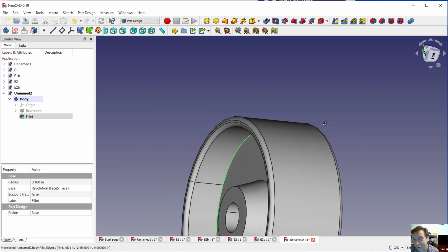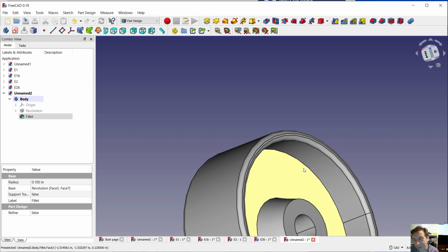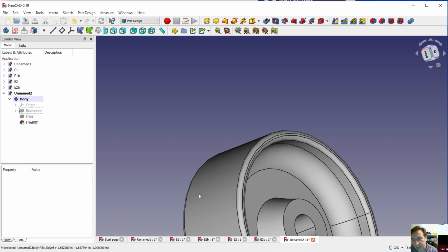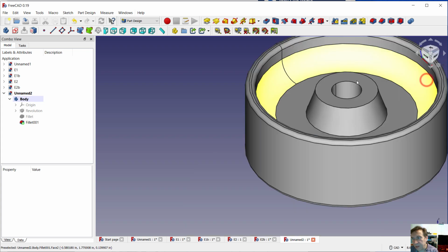All right. Let's try that again over here. Hold control. Click when you got that edge. All right, now we could go to fillet. We're going to put a big one in on here, so let's go with 0.5, so a half inch. And isometric.